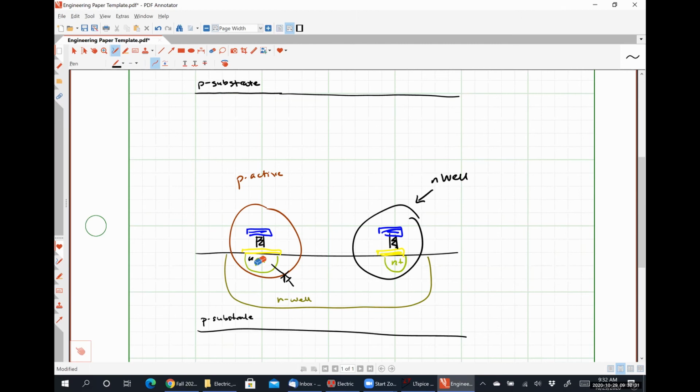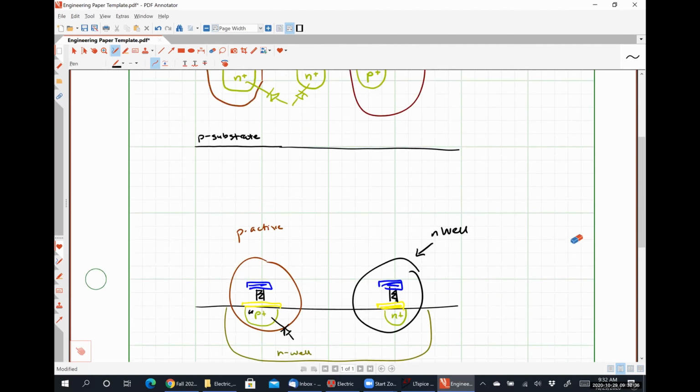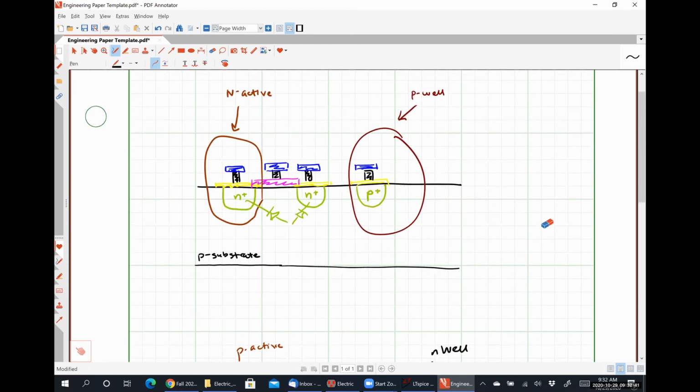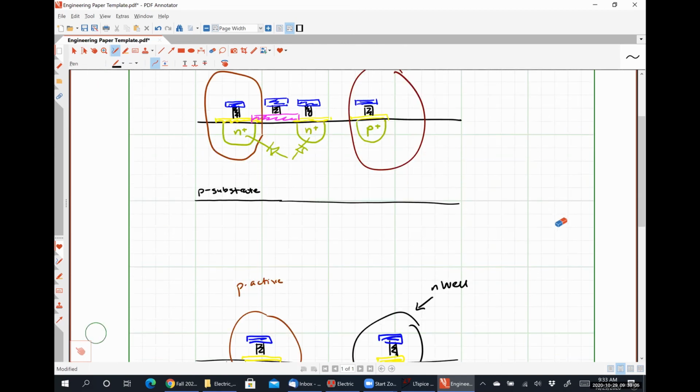All right, cool deal. Any other questions about what any of this jibber jabber we're doing means? I know it can definitely be confusing because you're thinking, okay, so I got an NMOS transistor, everything's supposed to be N except the body connection because that needs to connect to the P well, and it's not remotely intuitive. You really have to think about, oh God, do I want a diode or do I not want a diode as to what you put where? Which can be cumbersome.